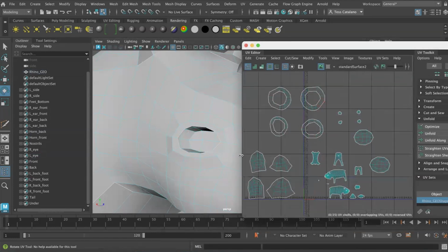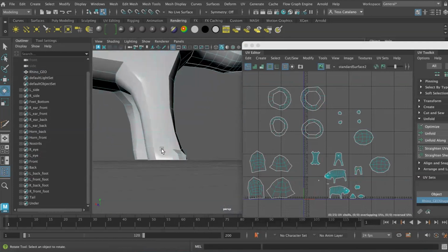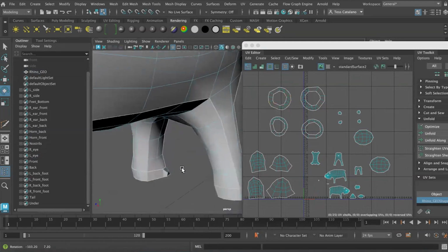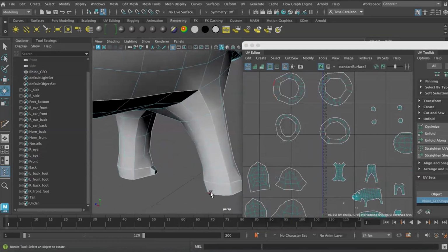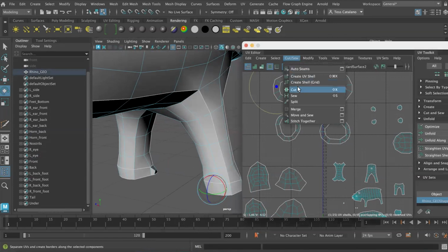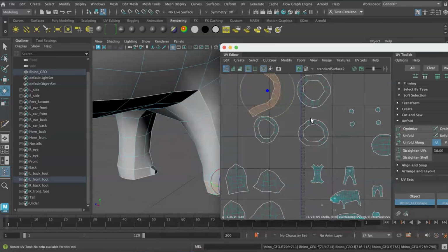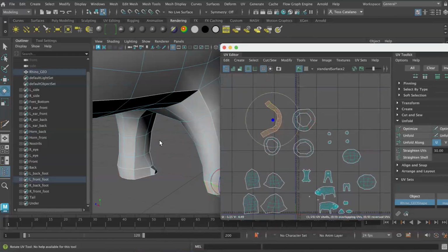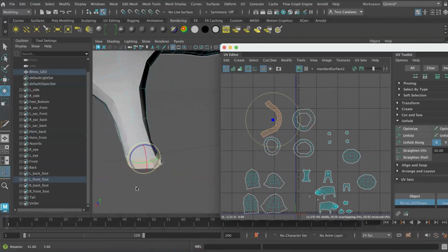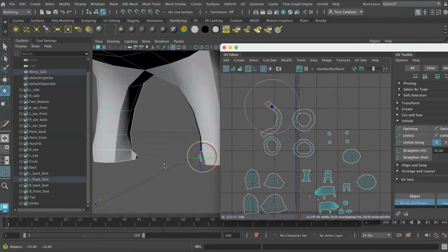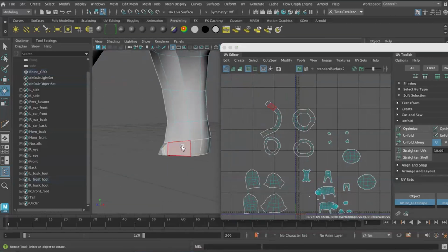Now let's look at these feet here and decide, I think maybe this edge in the back, right? I'm going to want to cut this as well. I don't want it to be positioned this way. I really want that texture to be applied this way and then maybe make a seam here in the back. So this is my front and I'm going to select, let's select that edge and we'll say cut. And then we will select this shell, go to face mode, say unwrap or unfold. And that may be better. Then let's do, although we can say maybe optimize. Still don't love the way that this particular face is pretty big. Guess it's okay. Guess it is big here on the model too, so that's fine.